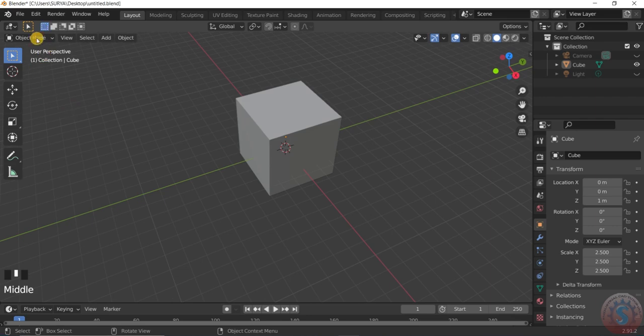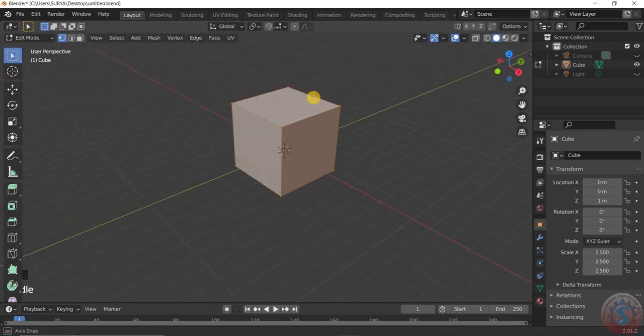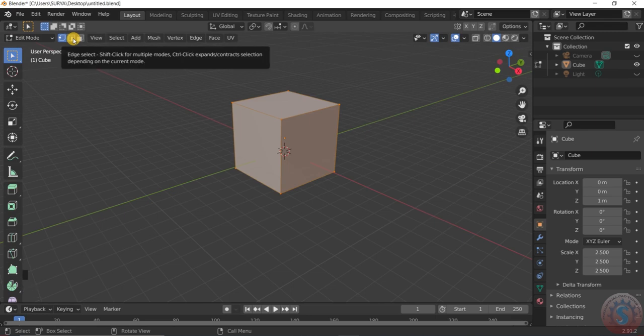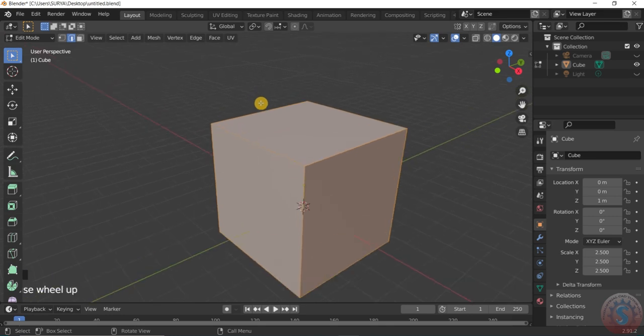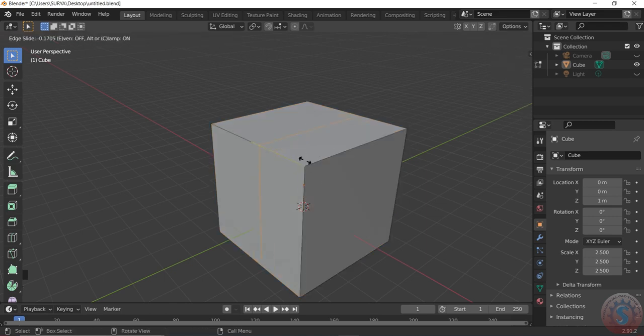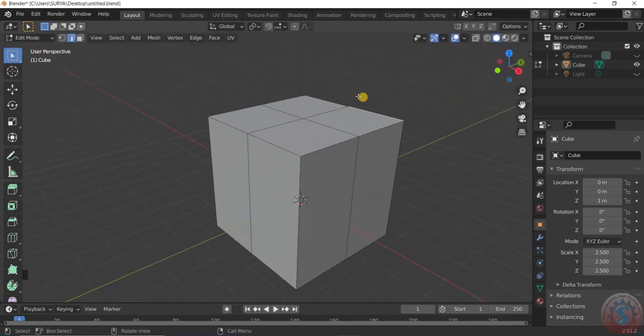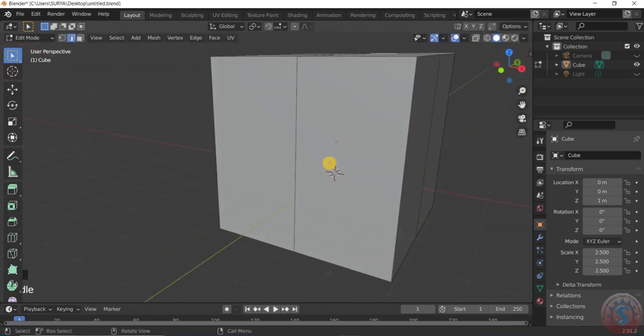Then after I am going to the edit mode. You can observe the edit mode, and go into the edge by using Control R. Give the loop cut. I want one here, using the escape key and the left mouse key. Again give Control R in the vertical direction and the horizontal direction. Give the escape key and the left key. You can observe one of these is created.